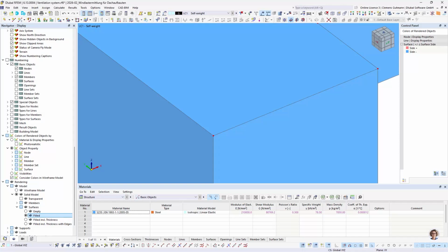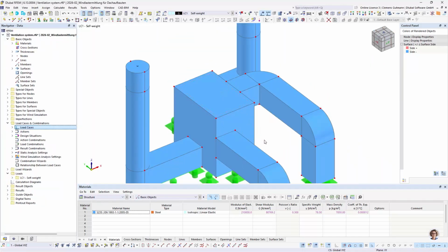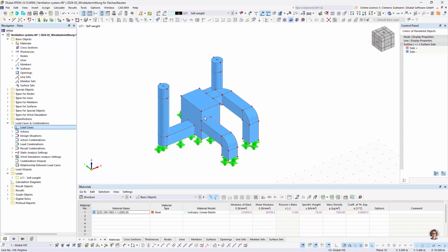So what we introduced is a so-called shrink wrapping. So it is basically what it says. We are shrink wrapping a geometry. So we are putting a polygon mesh above this structure, and we can decide how fine or coarse this polygon mesh is. And this wraps around the structure and generates automatically a closed hull, and hence produces a calculatable CFD model.